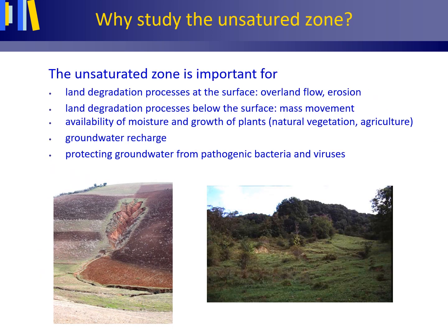Soil water can be considered as important in many ways. With regard to land degradation processes, the photo to the left shows that if on a hill slope the precipitation intensity is larger than the infiltration rate into a soil, overland flow and gully erosion can occur. Too much water in a soil can cause mass movement. The photo to the right shows a hummocky appearance of a hill slope due to small mass movements, so-called soil creep.